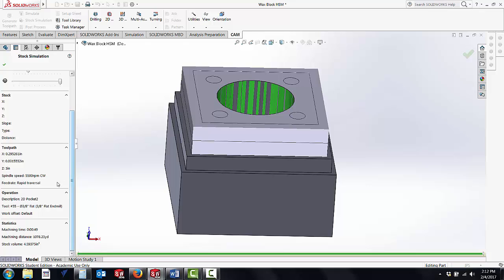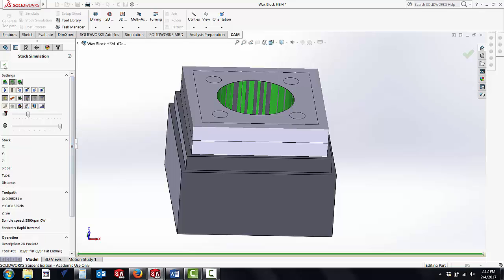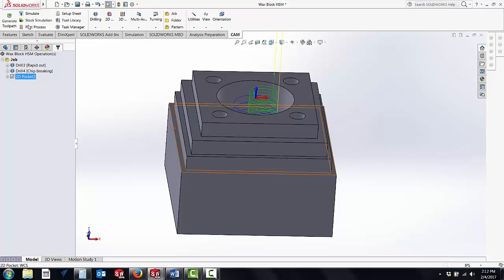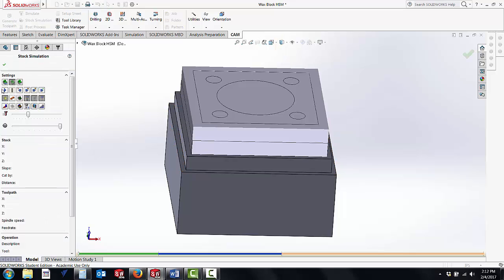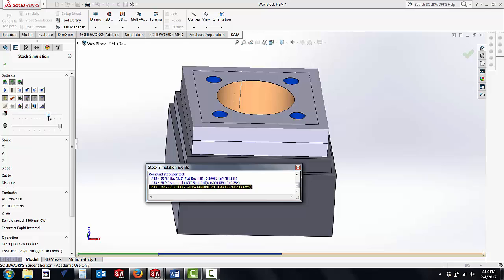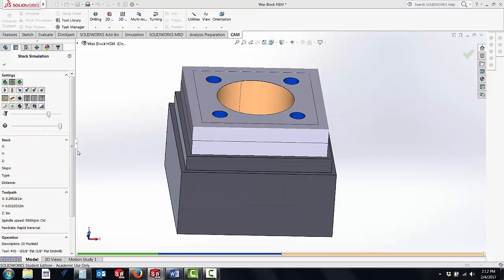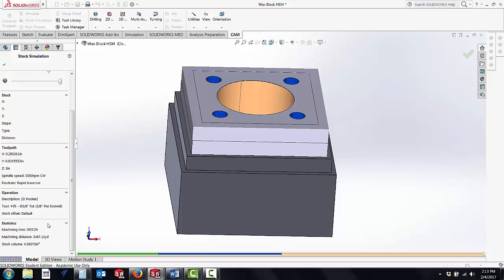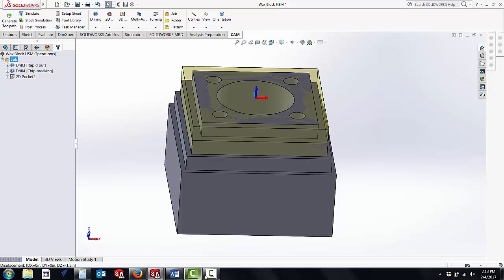So far, looks like our machining time is 49 seconds for that particular operation. Let's see where we're at overall. Select job. Hit go. And I can make this happen really fast. We are at 2 minutes 24 seconds. Here are the operations so far in these colors, so you can see that that pocket took just as much time as the other two operations. All right, another one done.